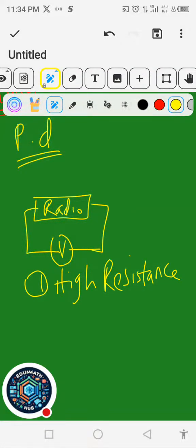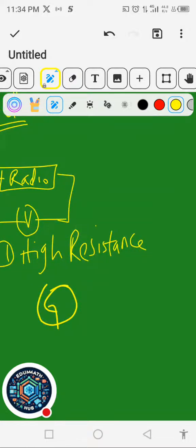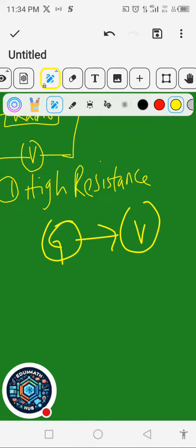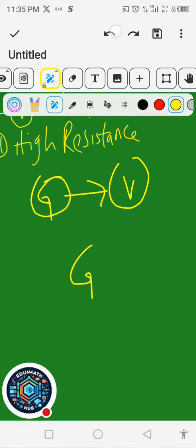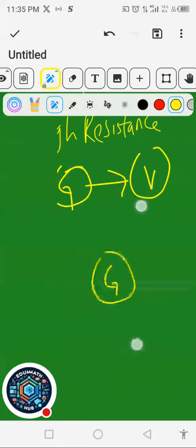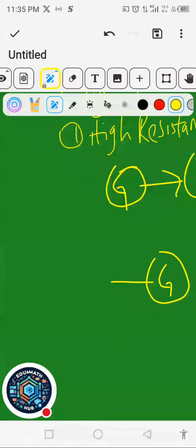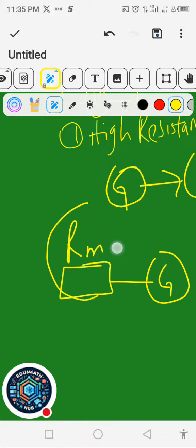Then the next thing, to convert galvanometer to voltmeter, this one is very simple now. To make it a voltmeter, you have to connect a high resistance multiplier. So this is a galvanometer here. You want to turn it to a voltmeter. This is how you connect it. You connect a multiplier. Multiplier just means a resistance that has a very high value.